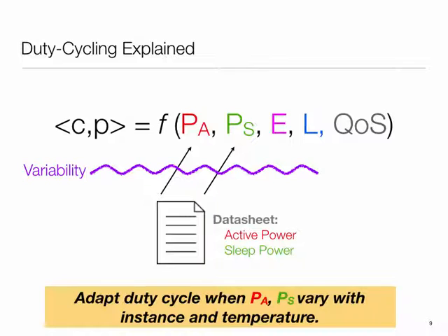So basically you can declare a cyclic function. That's kind of a notion for duty cycling. And then whenever there's nothing to run, the OS puts the system to sleep. In other cases, you can kind of fake it. For example, if you're running on Linux, you would arrange for the system to go to sleep, and when it wakes up, you execute your function, and then again make a call to sleep. So there are many different ways you can realize duty cycling.